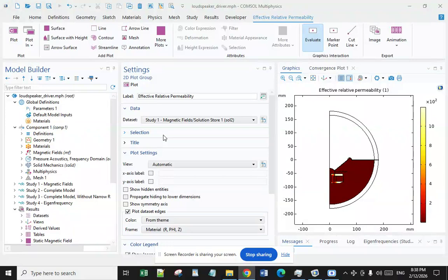The third disadvantage can be size constraints. Although there are electromagnetic acoustic transducers as small as a penny, commonly used transducers are large in size. Low-profile electromagnetic acoustic transducer problems are still under research and development due to their size constraints. Electromagnetic acoustic transducer phased arrays are also difficult to make from very small elements. The fourth one is that caution must be taken when handling magnets around steel products.